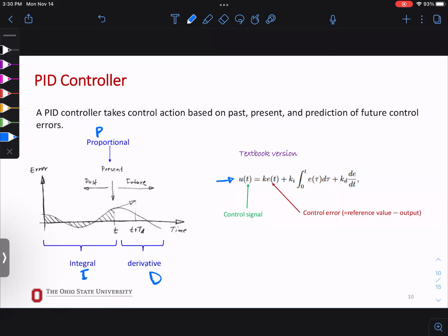So the element that is in the present, proportional, is multiplied by a coefficient called K, well, KP usually. So proportional is KP, I'm gonna add P here. So we multiply that by amount of error directly. So how much error do you have? I have 10 centimeter error. Okay. Multiply by a value that drives this to 0, right?